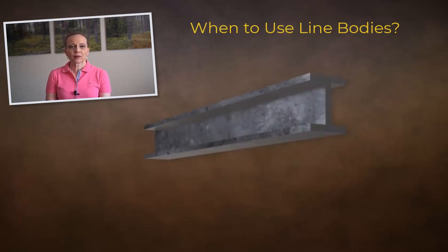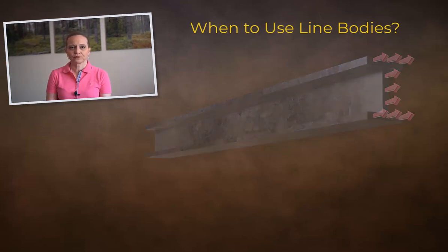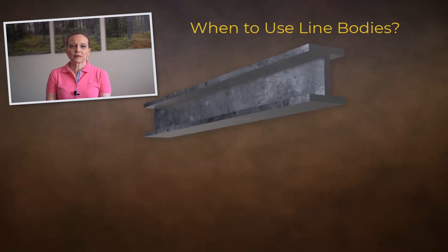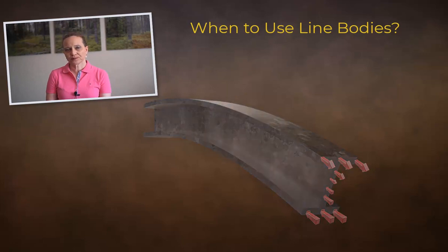If we take the beam and apply an axial load, the beam will stretch or strain, and we will generate normal or axial stress acting along the length of the beam. Now let's take the same beam and put a moment load to bend it. We see that the beam has curvature to it, and its curvature causes strains to develop through the cross-section that vary from the extreme fibers, or top to bottom, if you will. But again, these strains and associated stresses are still acting in a normal or axial direction of the beam.